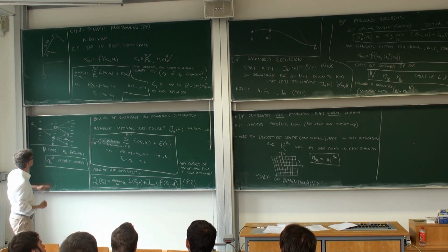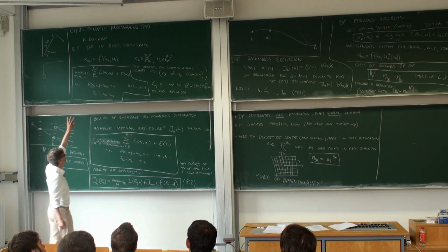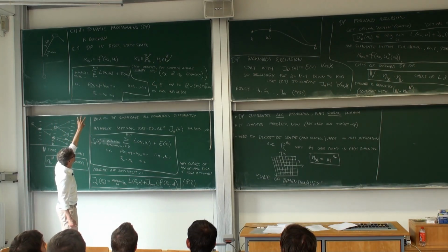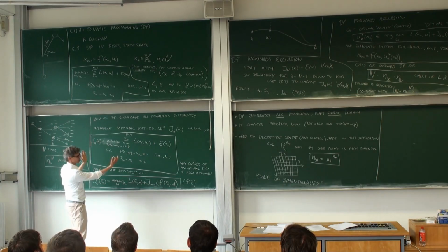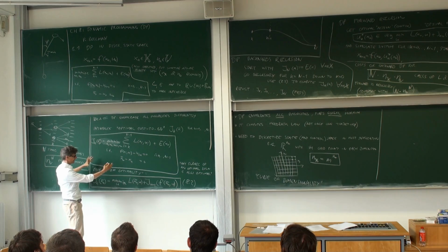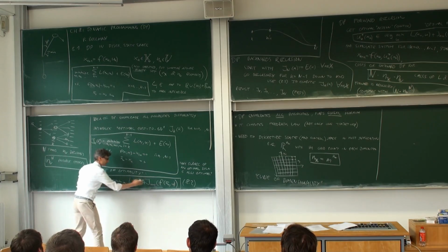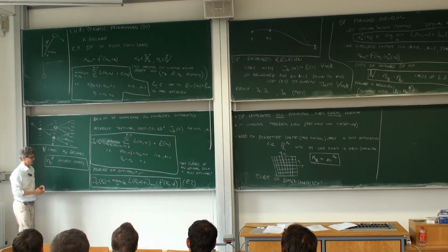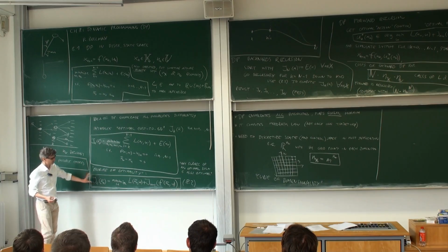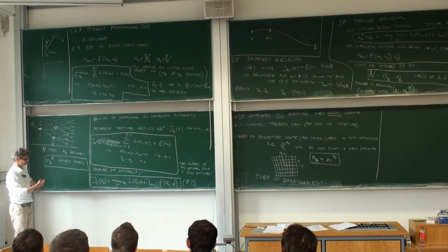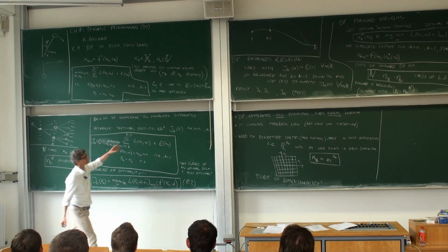So what we did is we have an optimization problem, an optimal control problem, and we break it into, so to say, shorter horizon problems. We define the cost to go, the optimal cost to go, and then we defined a relation that the cost to go needs to satisfy, namely the cost to go at 2 consecutive time points is related to each other via this simple formula here. And this formula is the key for the backward recursion, what we described here.